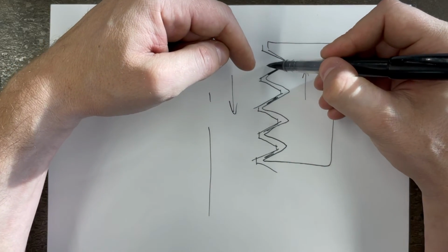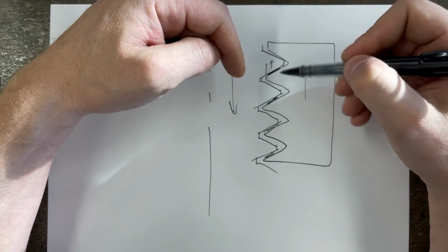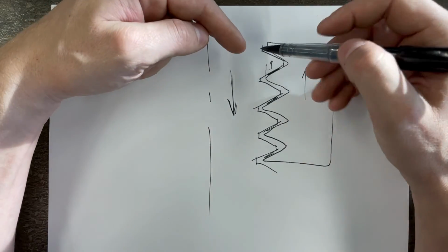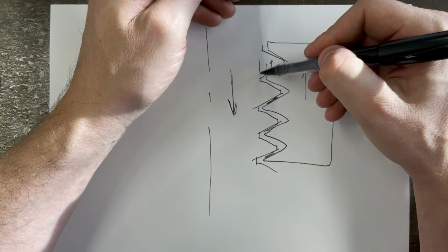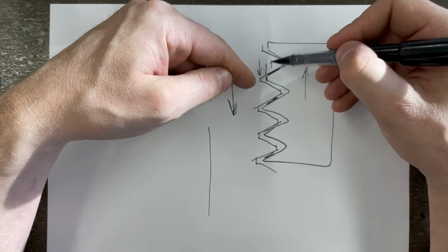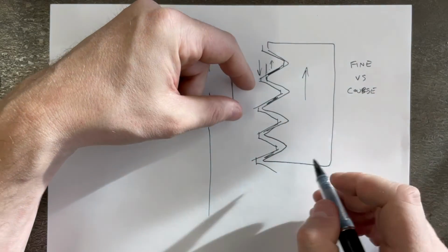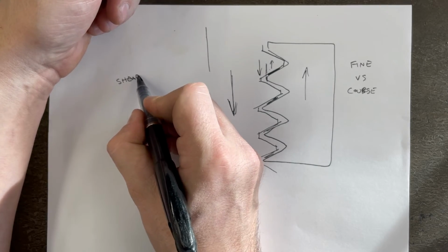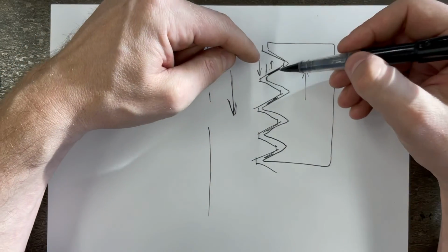So this nut is going to put a shear force through this plane where it wants to shear and pull the teeth off here, whereas this internal minor diameter to the inside of the nut is going to be wanting to pull this in the opposite direction. So there's a shear force that's being applied there. So that's one thing to remember, is shear force. The other thing to keep in mind is those opposing forces.